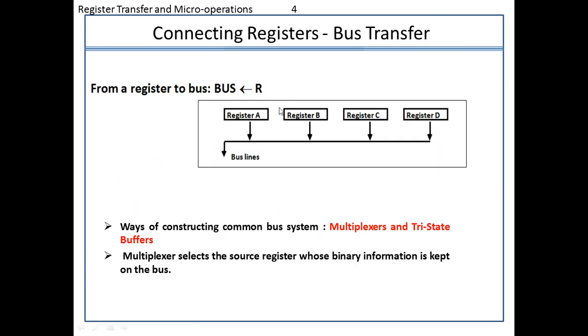So this is how we are designing the bus systems. As I was explaining earlier, if I have some number of registers, then for each bit position I will have some bus lines available, right? Again, if I take the example here, register A is there, and these are all of 2 bits: A0, A1, B0, B1, then C1, C0, D1, D0.